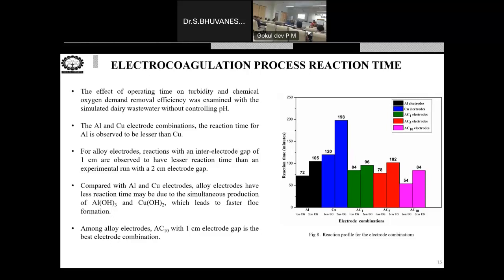If you take 1 kg, I will take 900 grams of aluminum and 100 grams of copper, and both will be put in the crucible in an induction furnace. We use an induction furnace for the melting. After about 1100 degrees, it will be in the molten state. At 700 degrees itself, aluminum will be in the molten state; copper needs a higher temperature.